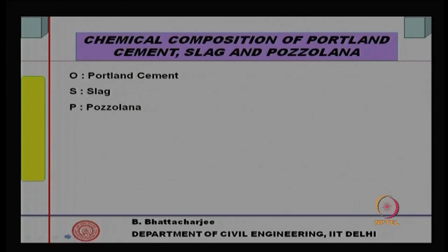When Portland pozzolana cement is produced with fly ash, what is done is you actually take the Portland cement clinker, one of the popular routes, there are other routes also, and grind the fly ash together with the gypsum to get what is called Portland pozzolana cement. By proper grinding and adding additives, you can compensate for somewhat slow strength development in case of pozzolana. Pozzolana strength development is relatively slow for two reasons. One, the reaction itself is relatively slow.